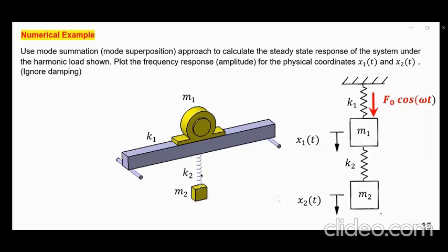Now attached to the bottom is another mass, through a spring. Stuff like this has a very practical use, and it is called a vibration absorber. Instead of this beam or that motor oscillating up and down widely, as it would without any attachment, we make it a 2 degree of freedom system by adding a spring and a mass here.